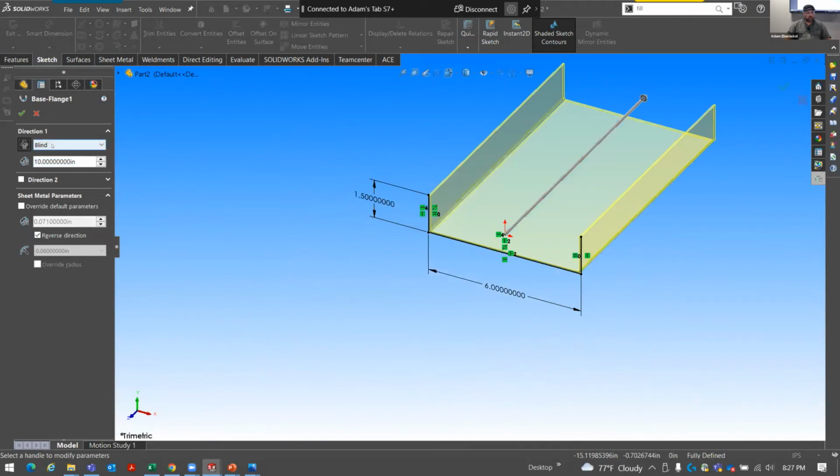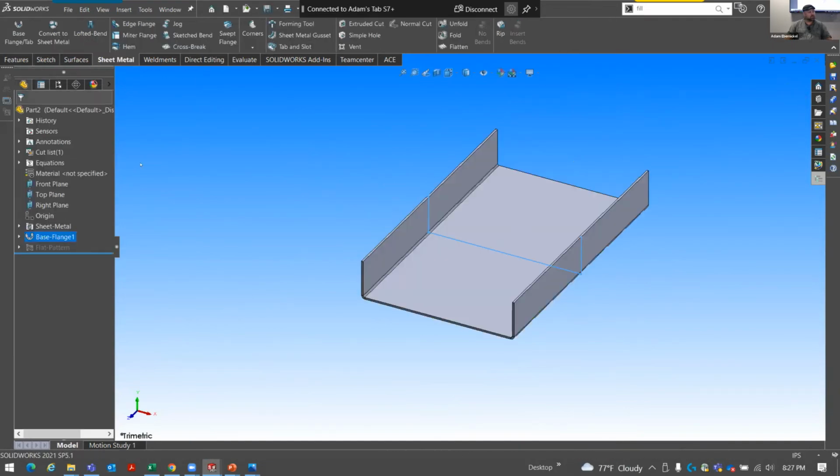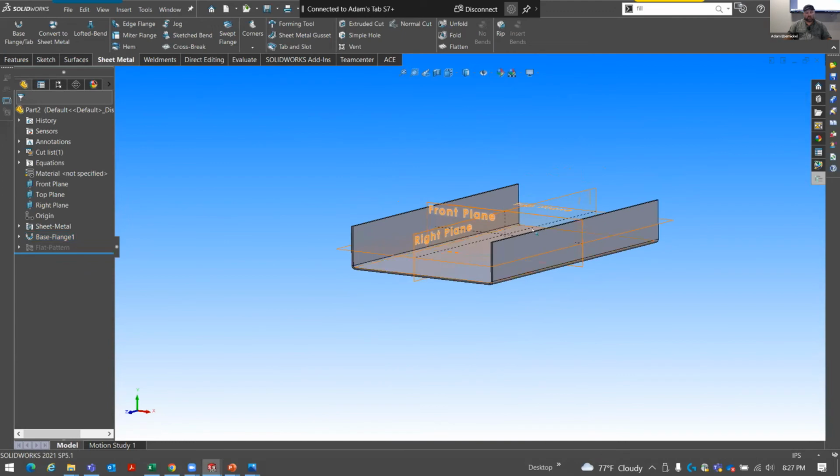But do we want to? What did we just mention? When all else fails, when in doubt, and you don't have a reason to set it one direction or the other, do it about its center. So now if we show these planes, they're going to be exactly centered with that sketch. That's just going to help you out with a lot of things when you're doing width mates or you're trying to locate centers on centers, and just a lot of useful functionality there.